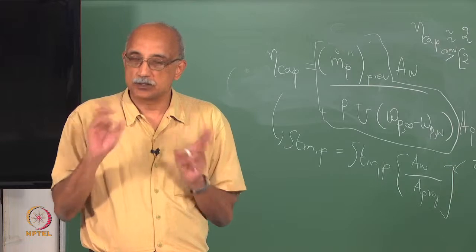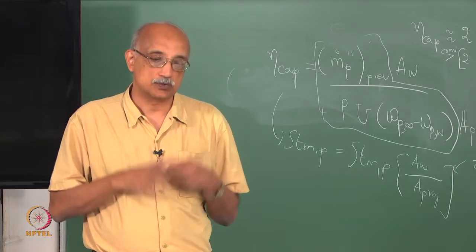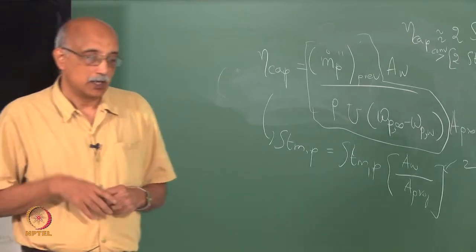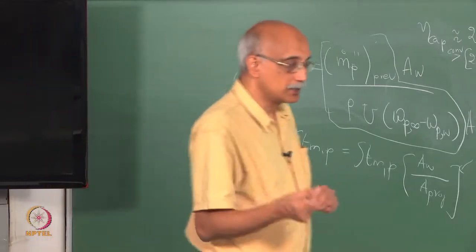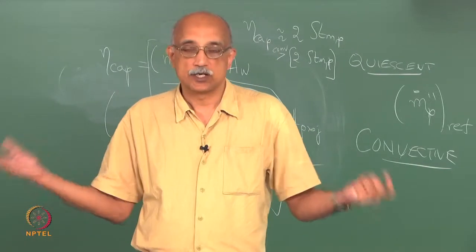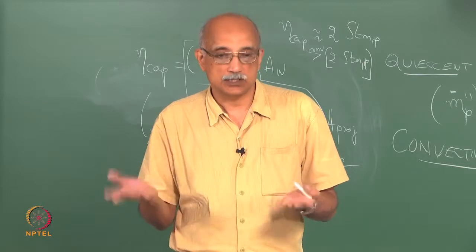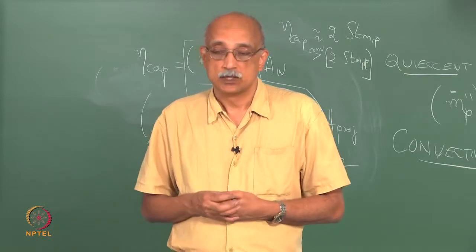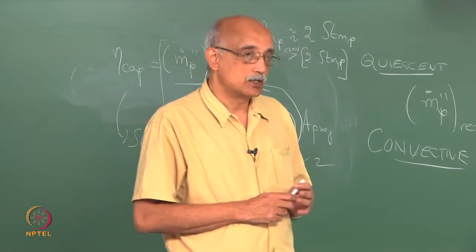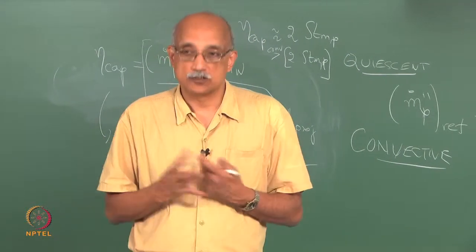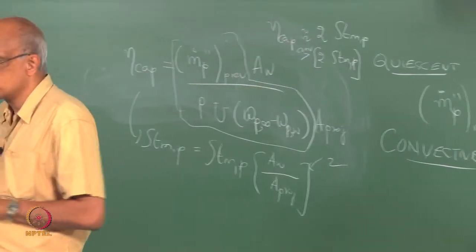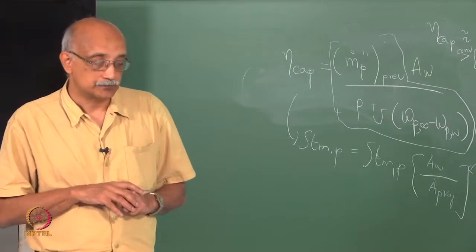Okay. So, it is very important to differentiate between capture efficiencies due to the inertial mechanism versus overall capture efficiencies, and this has to play into your strategy. If you have a process in which you are trying to minimize particle accumulation on a surface, which sometimes results in material loss in your system, then you have to consider this in a very holistic way and try to minimize your overall loss of material rather than loss of material due to a single specific mechanism.